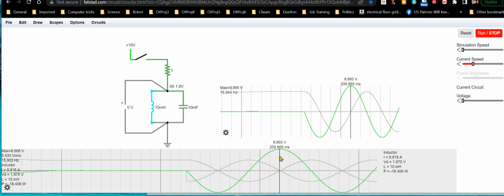But now the capacitor has all the energy, so for the next quarter cycle, the energy is going to bleed out of the capacitor and start to charge the inductor again. So, you see the inductor current start to rise, and at the same time the capacitor current rises, because that's where the inductor current is coming from, the capacitor current flowing in the opposite direction. So, these currents continue to increase as the voltage drops, since the capacitor is